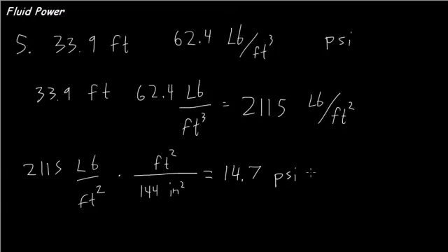Now remember, these are relative to atmospheric pressure, so these are gauge pressures. So I gave you a pressure measurement here that corresponded to atmospheric pressure, but it's just a coincidence. So if I were to convert this to absolute, it would be 29.4 psi absolute.